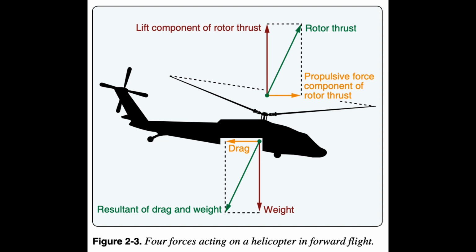Accordingly, by moving the air over an airfoil, we can change the static pressures on the top and bottom, thereby generating a useful force, an aerodynamic force. The portion of the aerodynamic force that is usually measured perpendicular to the air flowing around the airfoil is called lift and is used to oppose weight. Drag is the portion of aerodynamic force that is measured as the resistance created by an object passing through the air, or having the air passed over it. Drag acts in a streamwise direction with the wind passing over the airfoil and retards forward movement.